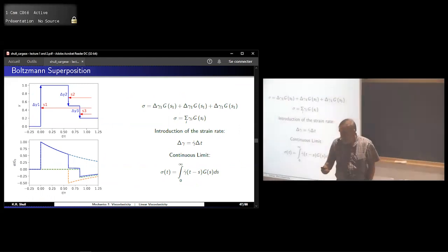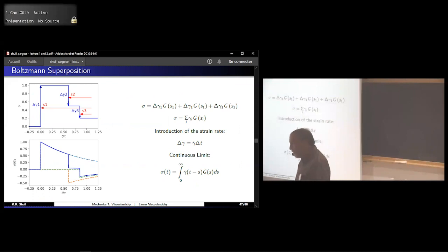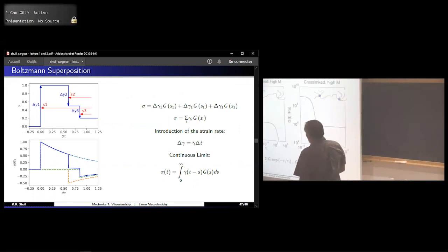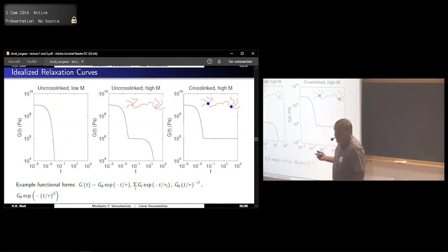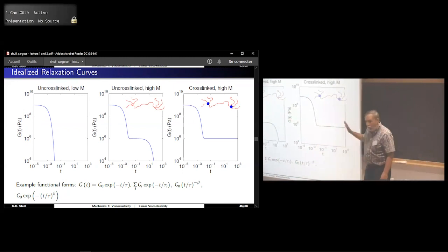Yep. Is that the relaxation of just the elastic modulus, or is the viscosity also in there? Well, it's got units of an elastic modulus, so units of a stress, but it's time dependent. These things are just different fitting functions to express the time dependence. So it's no longer a constant anymore. It's a function, right? These pictures are all just representations of some time dependent function. It can be for the elastic modulus, and it can also be for the viscous modulus. Viscosity, elasticity, it's all in here, right? So I do the same thing for a liquid. At this point, it says nothing about whether it's behaving more solid-like or liquid-like.